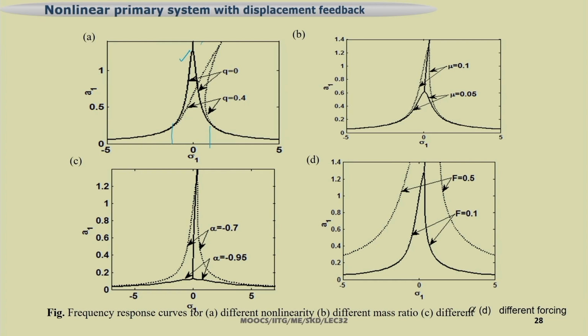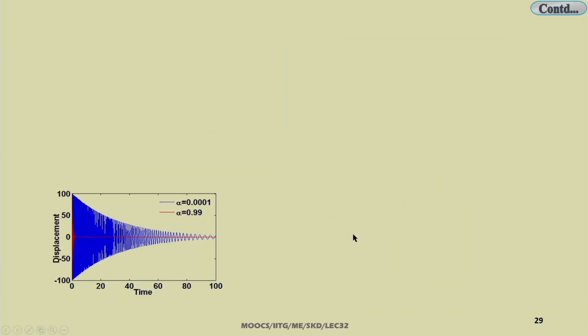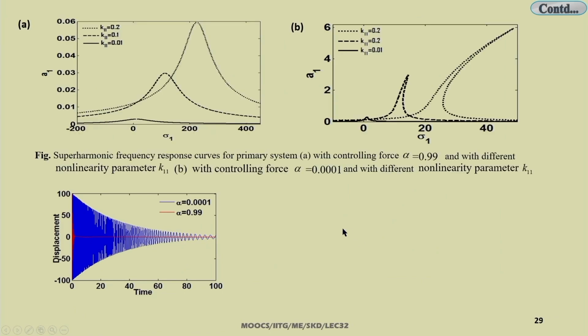By changing different control parameters, we can observe what the response amplitude of the system will be. The response amplitude of the system can then be controlled passively by controlling those system parameters, or actively by applying this voltage and controlling the piezoelectric material property.